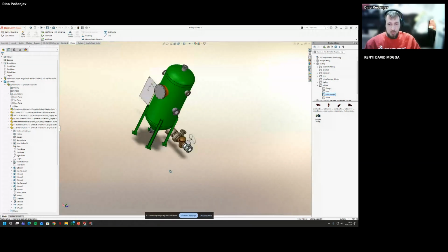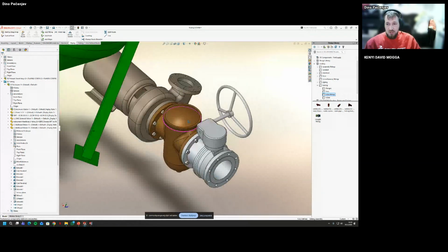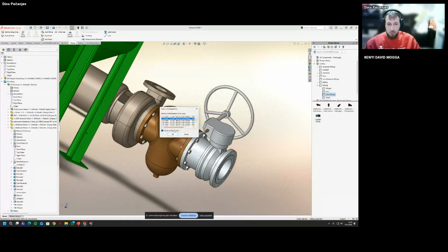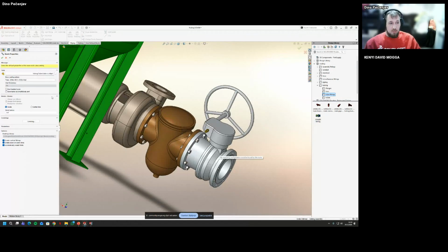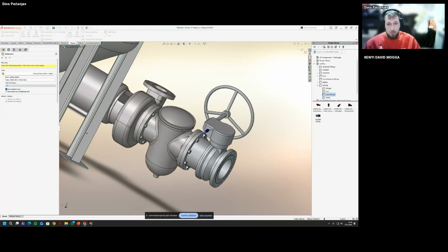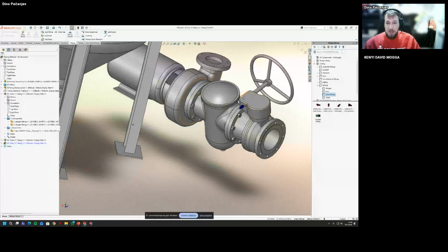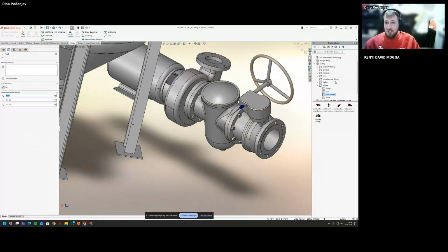So what we're going to do, we're going to start routing. So I'm just going to put it here. We're going to use the flexible hoses for this route, the template we have made. And okay, so this is started. And for the clips, I can use the tubing clip. So again, it uses the mate references. I can use the shift and right arrows to rotate the route.